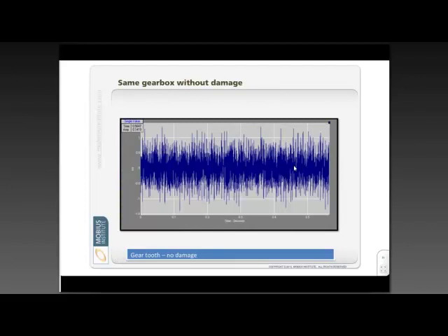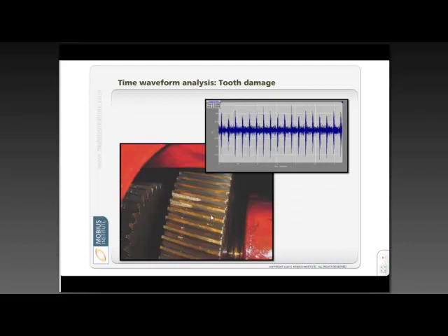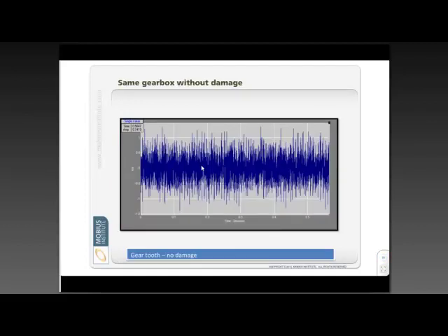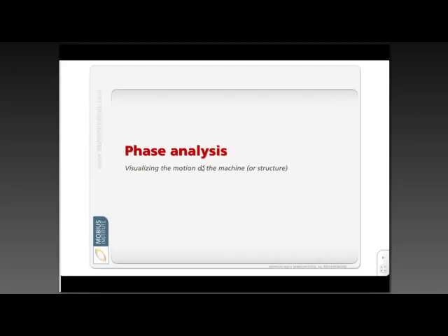This time waveform, you might think, oh man, there's little spikes, there's big spikes. But based on the amplitudes and the fact that it's fairly uniform, that's a time waveform that I would look at and say, I don't need to look at it anymore. There's nothing interesting. If I know I'm collecting it properly, it's all cool. This is actually this gear when there are no broken teeth. That's a zoom in on this particular area there. So it's just healthy. I would look at it for 2 seconds, move on. That's fine. Okay, so we've looked at the time waveform and it tells us a lot.